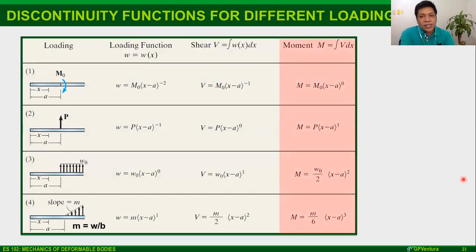So these are all externally applied loads, 1 to 4. Let's start with the simplest. If I see a moment, a couple, an applied moment such as this, or a moment reaction, look at this. It is very, very important. Look at the sign conventions. The moment function of an applied moment or a moment reaction is equal to m naught, or the value of that moment, x minus a raised to 0. So let's first define m naught as the magnitude of that moment.